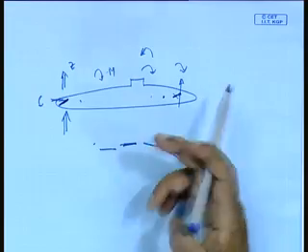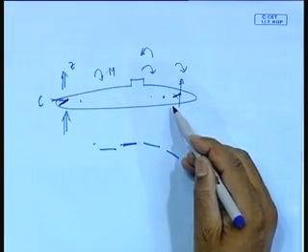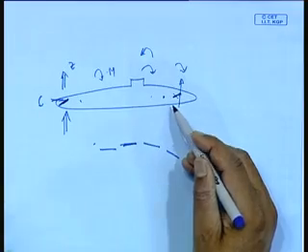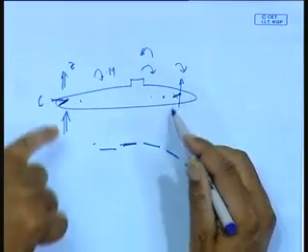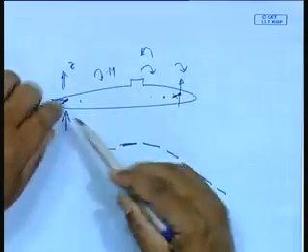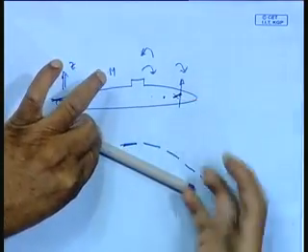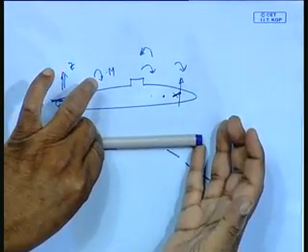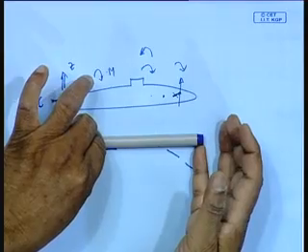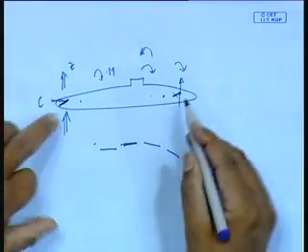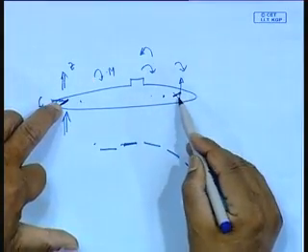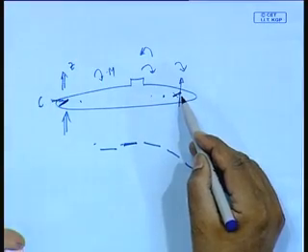You can never do that with one plane, because any one plane would always necessarily produce theta and z. What do you do? You have to use both the planes. This will try to nose down and this will make sure that you have an adequate moment up to keep it in the same draft. So, that is why normally in submarines you always have two.